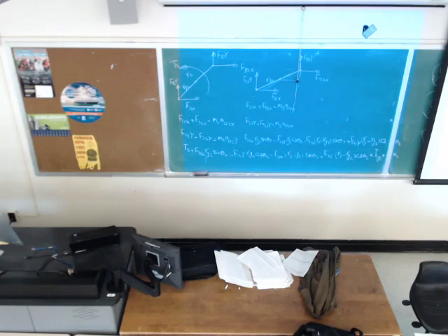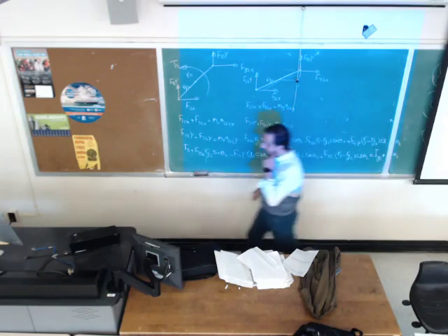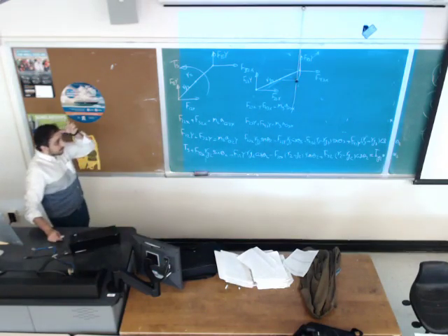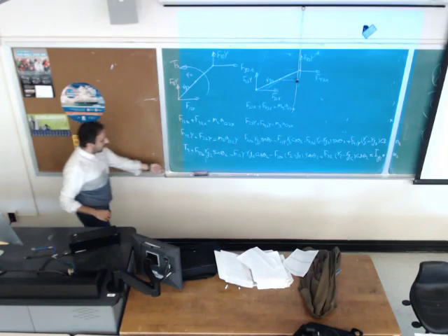And similar to link 2 and 3, I can write the moment or the torque that these 2 forces make about the center of gravity. And the right hand side will be IG4 times alpha. This is the last. So I derived all 9 equations so far.